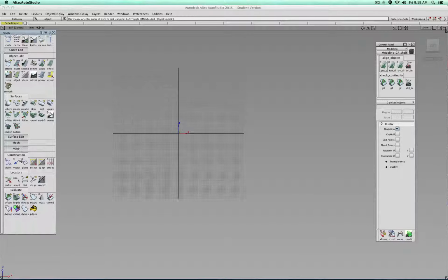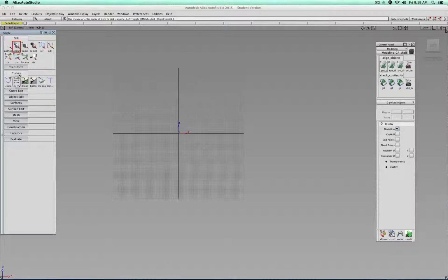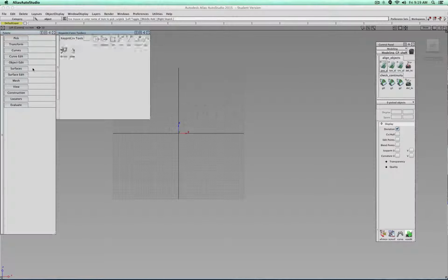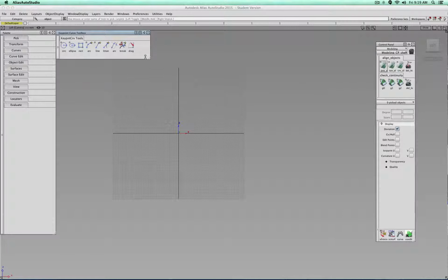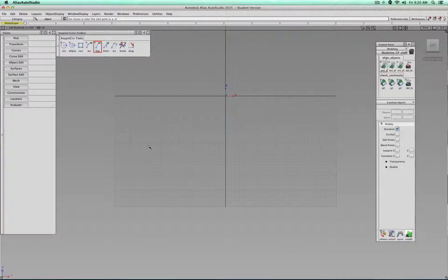Let me close all those parts here. And right click, key point curve toolbox. Let's make it smaller. And there it is. So I know that the lower base of my object is 62 millimeters wide. So I can click on this one and then with the Alt key, snapping to the grid, I click and click somewhere else till, for example, I get 62.